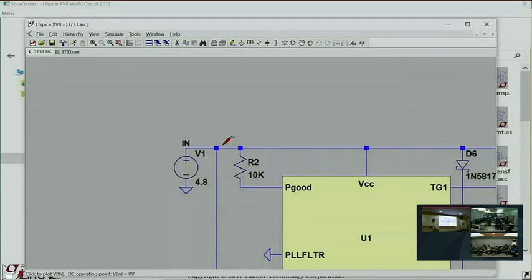Let me explain what's happening. All right, see, in this circuit, the reason why this filter capacitor here only decouples this circuit from the rest of the system is that it's not part of the design of the circuit. The reason why it's not part of the design of the circuit is because this circuit has an essentially infinite line rejection. Line rejection is how much output change you get for input change. So the thing is, say this input voltage here goes from 12 volts to 10 volts and it goes in 1 nanosecond.